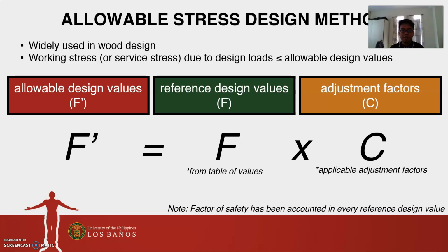The assumption is that the factor of safety has already been accounted for in every reference design value. So this F prime here would be the one to be compared with the working stress or service stress due to design loads.